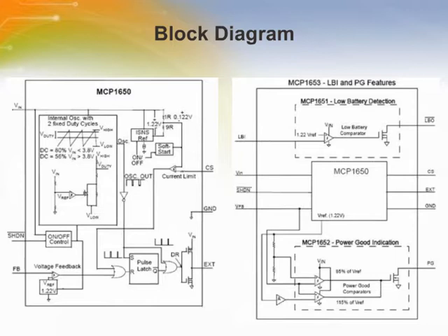When the input voltage is low, the duty cycle changes to a larger value in order to provide full power capability at a wide input voltage range. The output voltage regulation is accomplished by comparing the output voltage to a reference internal to the MCP1650, 51, 52, and 53.